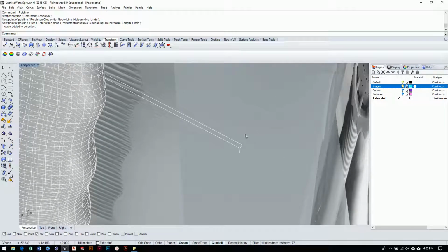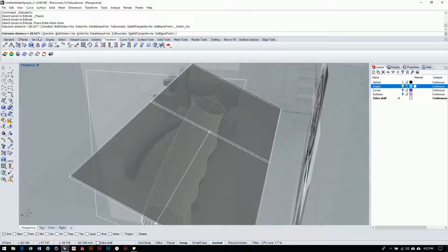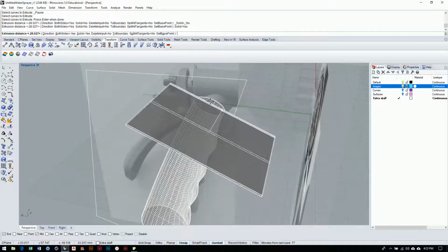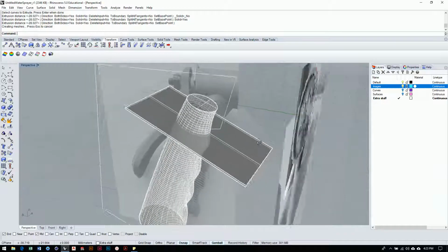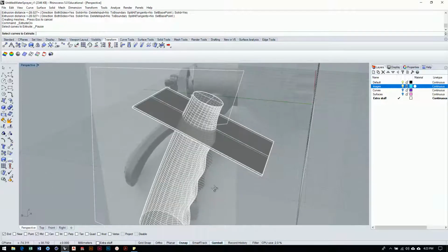So anyway, grab your extrude straight tool and get that rectangle, extrude it in 2 directions. So look at the command line. It should go both sides yes, solid equals yes, not no. Also, everything else looks good, so don't go too crazy with this thing. I mean, keep it manageable, but slice it all the way through the handle. And then go to linear array. It's right underneath rectangular array. It's right there, linear array.